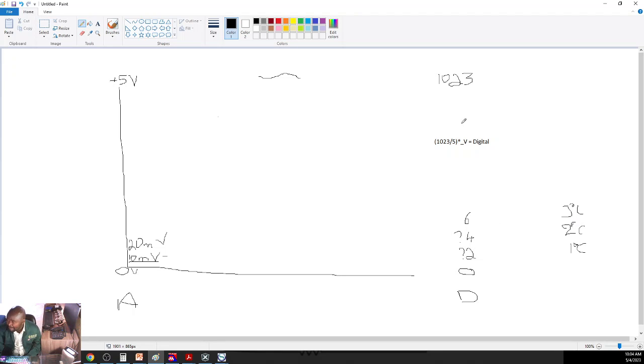So now in the PIC, after performing ADC, we'll have a value between 0 and 1023, depending on what the LM35 is giving in as analog voltage. We just need to take that value, divide it by 2, so that it can be temperature, because once we get it as it is, it's not temperature yet, it is just the ADC results. To convert those ADC results to temperature, we need to divide them by 2.